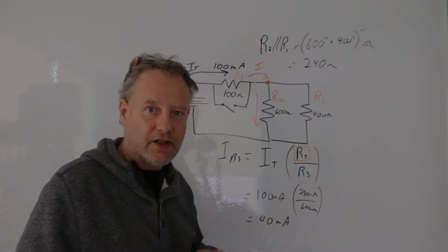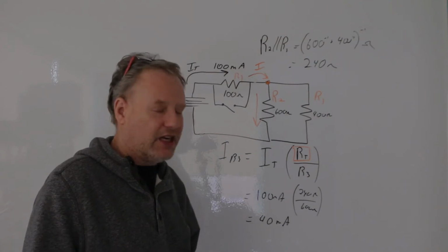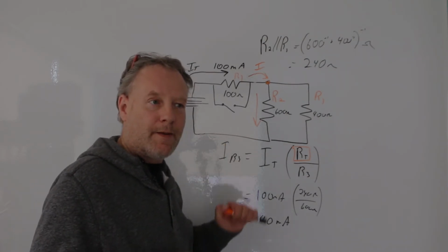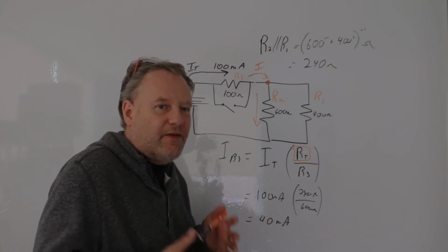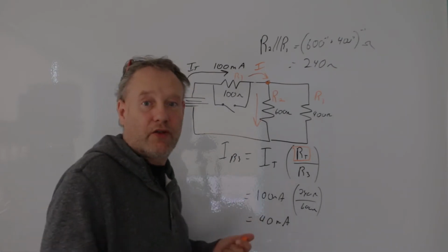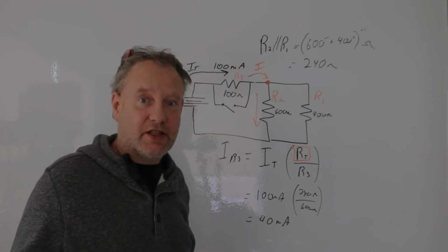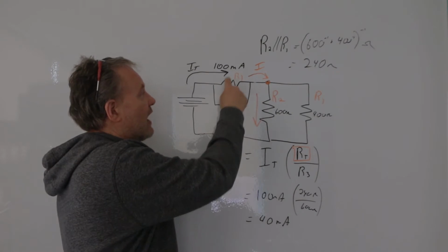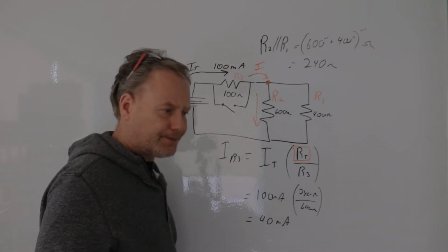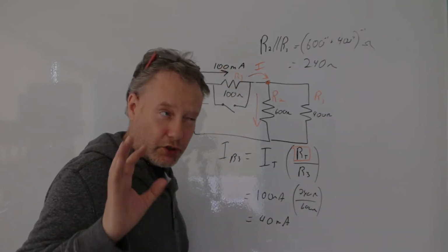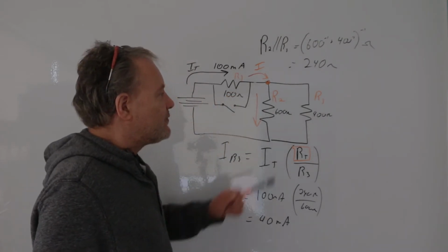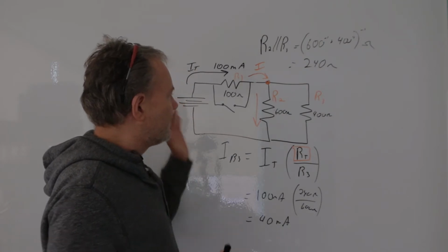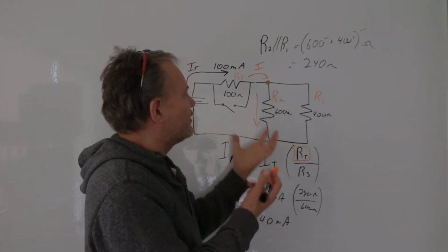So now, if you look at this, R1, it's not doing any division. All the current is going through R1. None of it is being divided by R1. I mean, the current actually exists because of the nature of R1. So if I were to increase or decrease that, this would increase and decrease. But all of the total current is going through R1. It's being divided amongst these. So these are the things that are actually dividing this current.